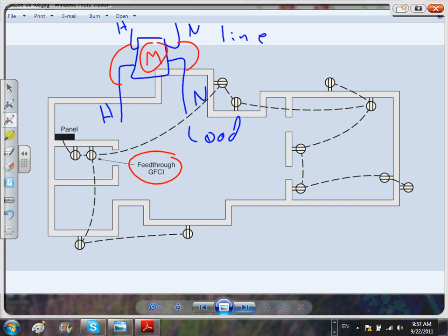It's outside, but it should be a GFCI, right? It's an outside receptacle. It should be a GFCI. Go to the circuit breakers, nothing. So I drove all the way there, charged him a certain amount of money, and you know what the issue was? There was a walk-out basement, and the electrician put a GFCI in the basement, which is now finished.